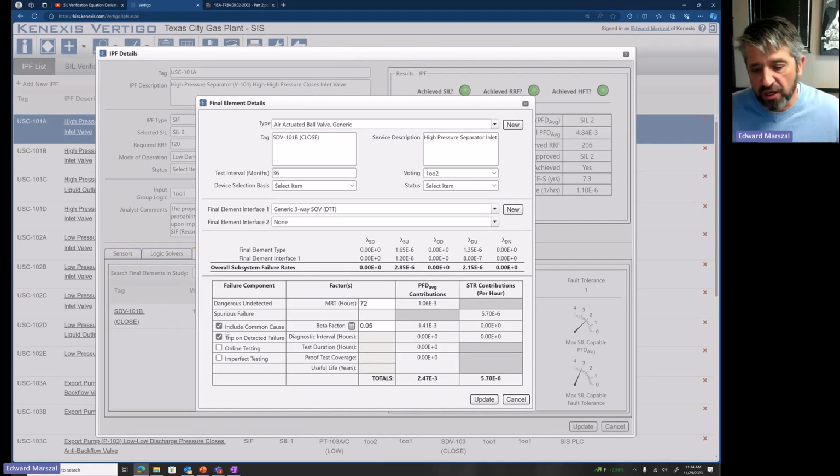Because your LOPA scenario begins with a frequency, which is a simultaneous, infinitely small time duration event, they are all independent of each other, and therefore you're not considering a cumulative effect that this independent protection layer is used in multiple places.